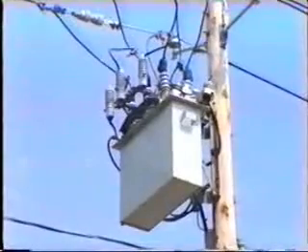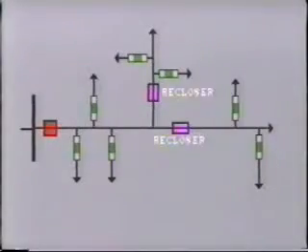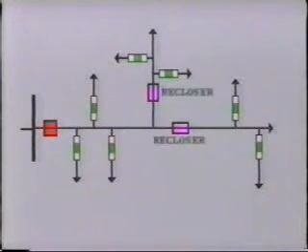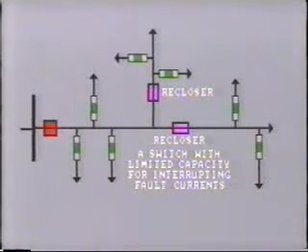On distribution systems, another more direct reclosing arrangement is often used in addition to the reclosing relays that we've been talking about. The device in question is known as a recloser, and it is usually installed in the line itself at some remote distance from the feeder breaker. Several reclosers may be installed, particularly at points where different sections are tapped off. The recloser is essentially a switch with limited capacity for interrupting fault currents.